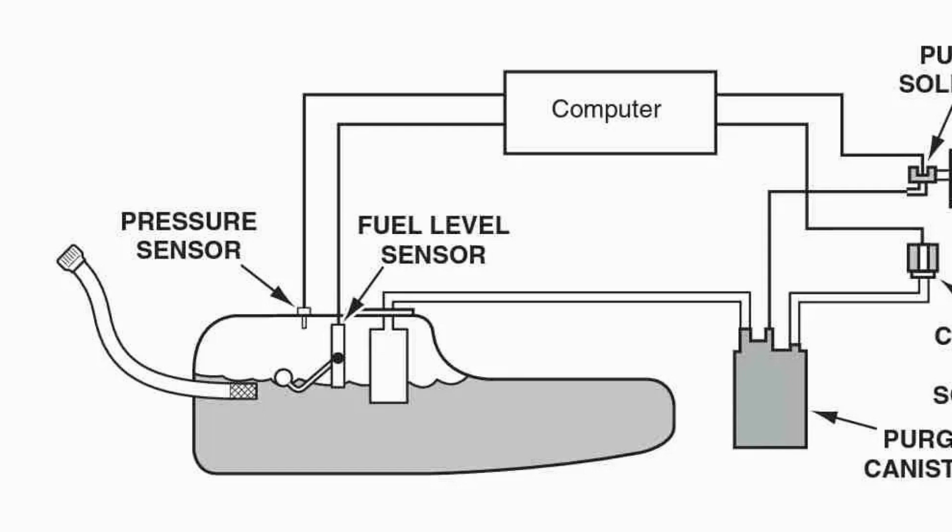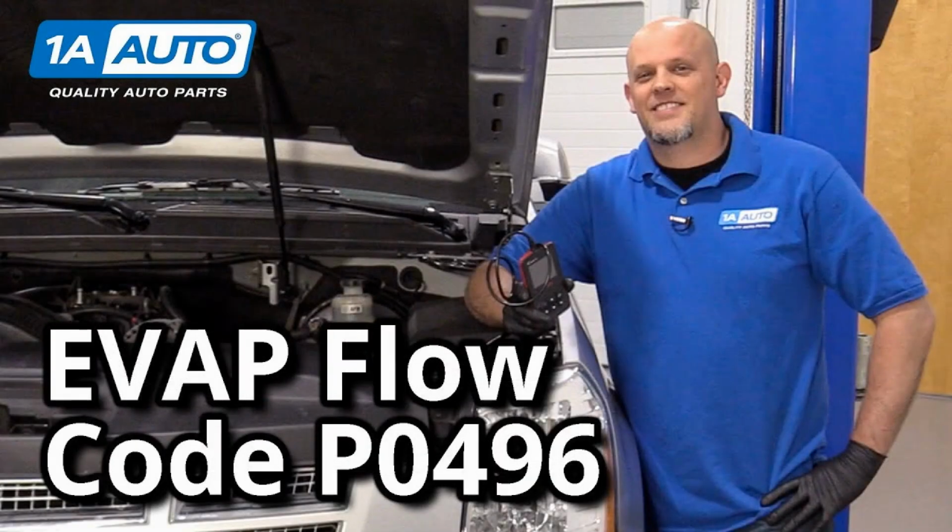Park your vehicle on a flat, even surface, away from other vehicles. Release all fuel pressure in your vehicle. Leave your vehicle switched off overnight to ensure that the exhaust is completely cool. Disconnect the car battery. Fold down the rear seat of your vehicle and lift the carpet, if applicable. Access your vehicle's fuel pump.